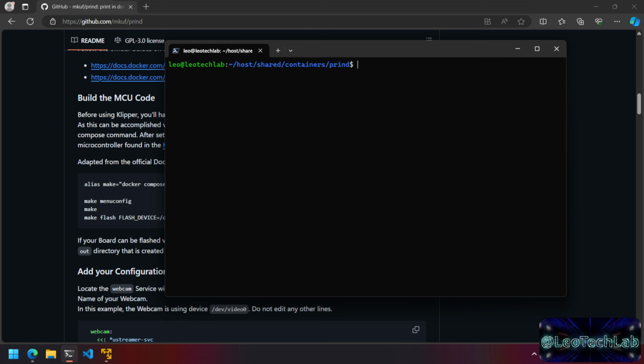But just in case you don't have the firmware provided, let's go through the manual process of creating the firmware step by step. To do this, we can use the Klipper repository, which provides us with a Docker image that already contains all the dependencies necessary for the firmware compilation. Regarding the specific firmware settings, it varies from printer to printer. Once again, I recommend using an online community for your printer, but in my case, the Klipper configuration file for my printer has the detailed instructions I should use to compile the firmware.